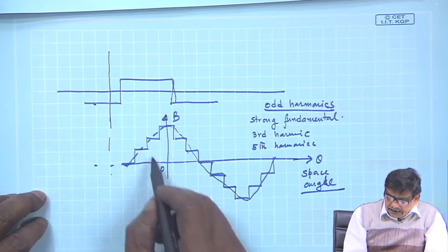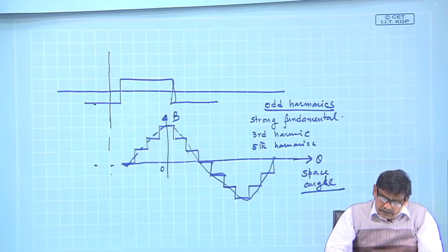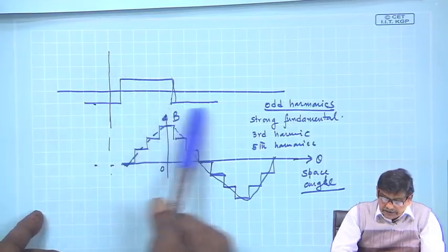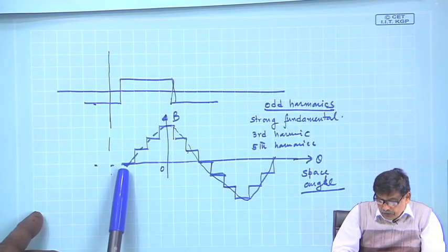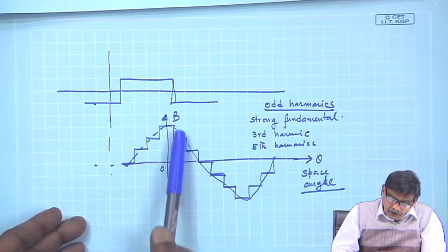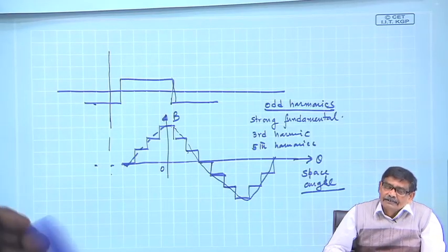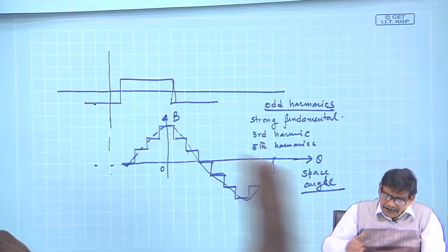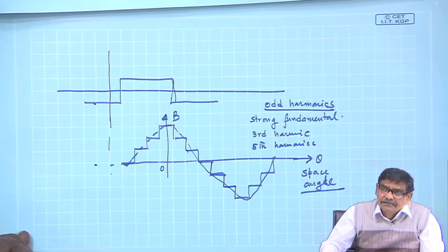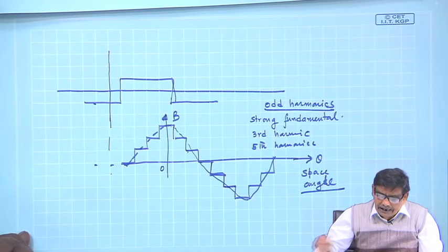With respect to that it will be like this, then we argue that okay, this waveform is not sinusoidal, but certainly better than the earlier proposition where a single coil was used, because it looks more like a sine wave, which mathematically means that the strong fundamental of this one is really strong, and third, fifth harmonics, well, any seventh, ninth, all these things will nonetheless have reduced and reduced amplitude, they can be neglected.